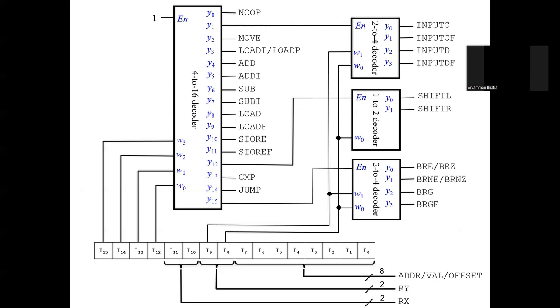The thing is that based on the operation we are doing, we want to have some control over which control flag, which control signal needs to be changed in what way, over and above the operation we are executing. So if your operation is loading into some register, you need control over which register you want to load into, which won't come purely from the operation, from the knowledge that you need to load.